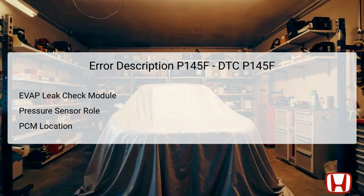The PCM, which processes input from various sensors, is usually located in the engine compartment and is responsible for making adjustments based on the data it receives. When the pressure readings fall outside of predefined parameters, the PCM detects an irregularity and registers the DTC P145F, indicating a potential leak or malfunction within the system.